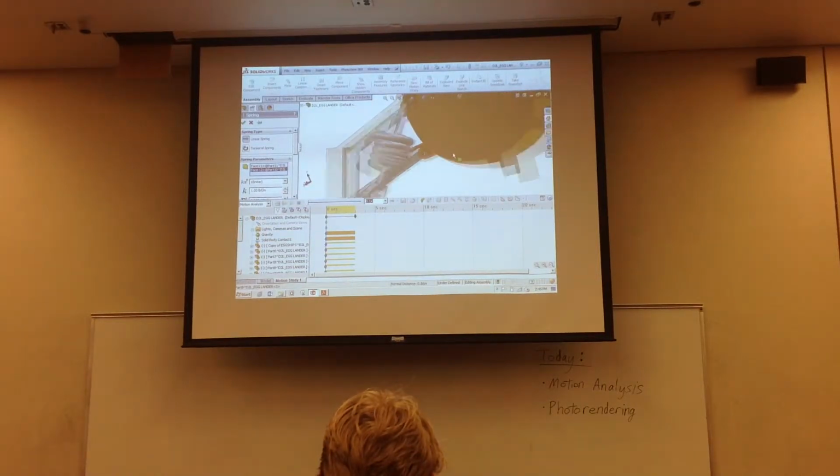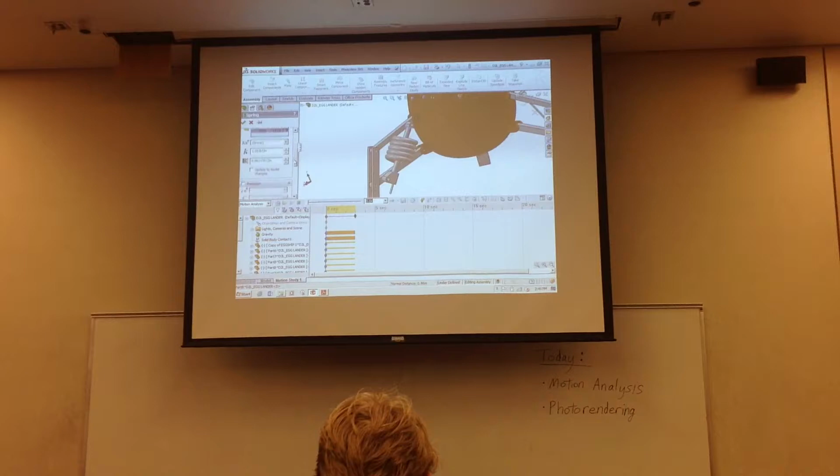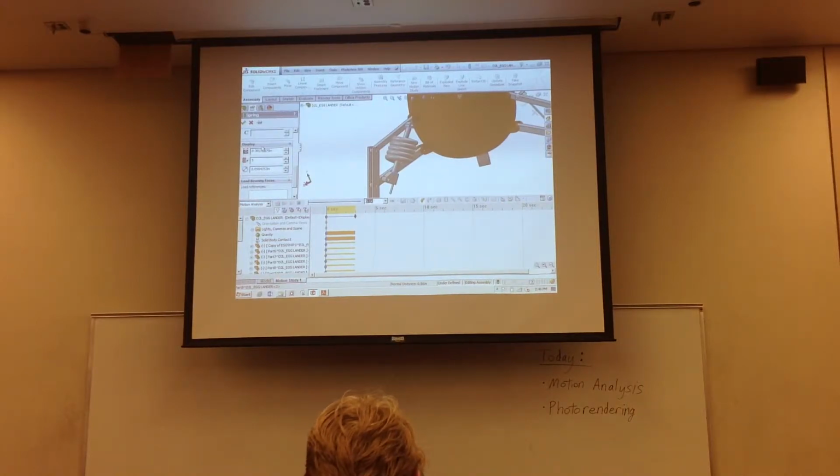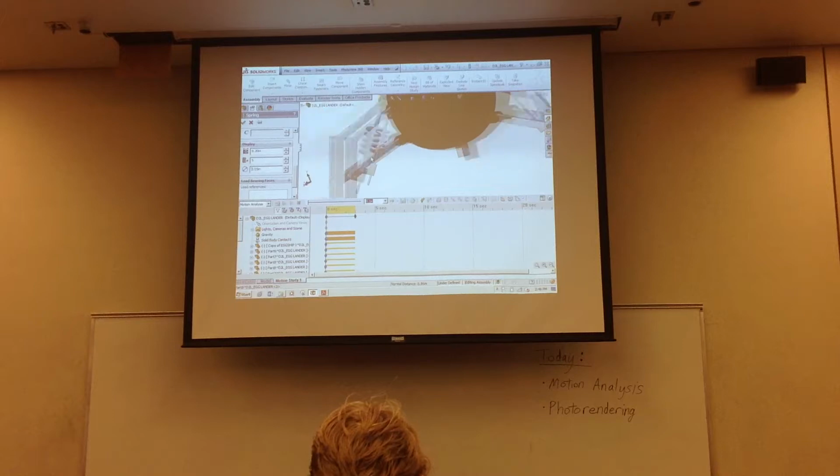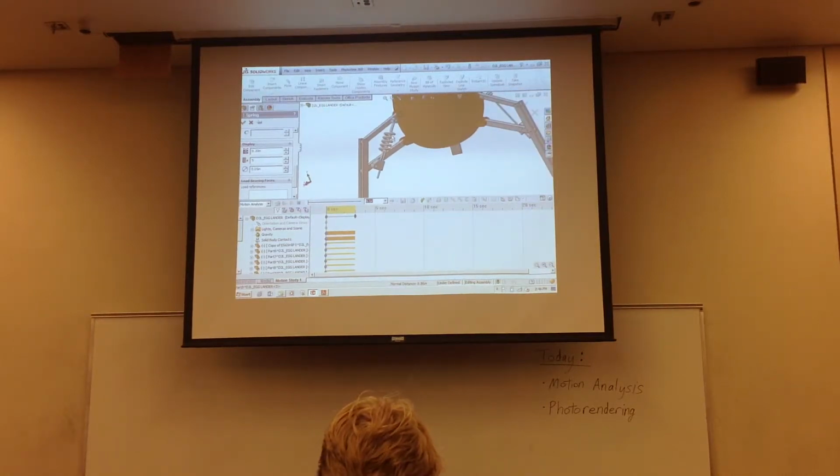We can make that look a little more realistic for our application if we scroll down here to where it says display. Okay, we can set, let's try for the coil diameter, let's say 0.2, number of coils 5, that's fine, but let's make them a little smaller for the wire diameter, let's say 0.05. So that looks a little more reasonable. Okay, but that change did not affect the physical properties of the spring. That was only changing the way it's displayed on the screen. To control the physical properties of the spring, we go back up and change the spring parameters, like the spring constant K or the exponent.